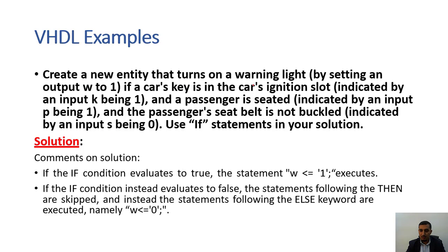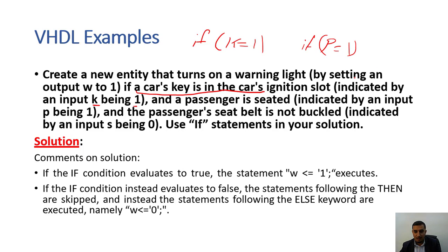Create a new entity that turns the warning light on if car keys are in the ignition, indicated by K equal to 1, and the passenger is seated, indicated by P equal to 1, and if the passenger seat belt is not buckled, indicated by S equal to 0, then we have W. So there is another if statement. We can do all of this using if statements.